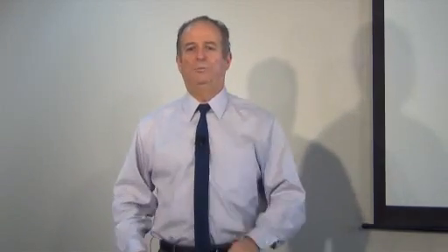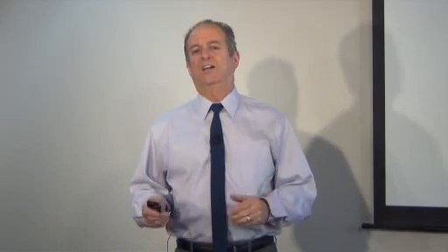So I want to really point that out. You'll hear I squared R losses mentioned all your career in power systems because people are trying every day to reduce that, whether they add capacitors, and we'll get into that, or whatever they do to the system, reactive resources, whatever they can do in the system to cut down on current in order to increase the power flow capability or decrease losses. We want to decrease losses as much as we can.